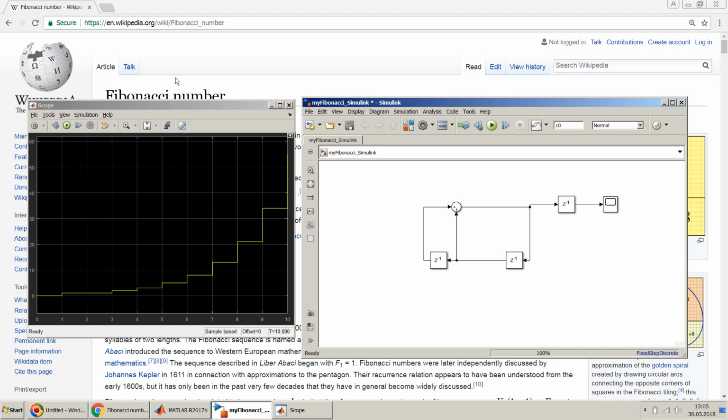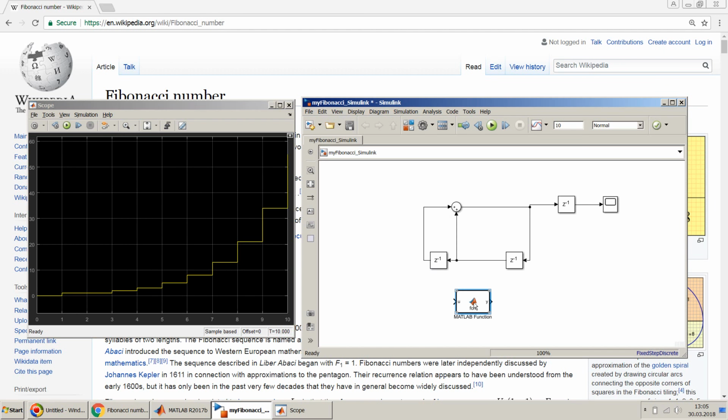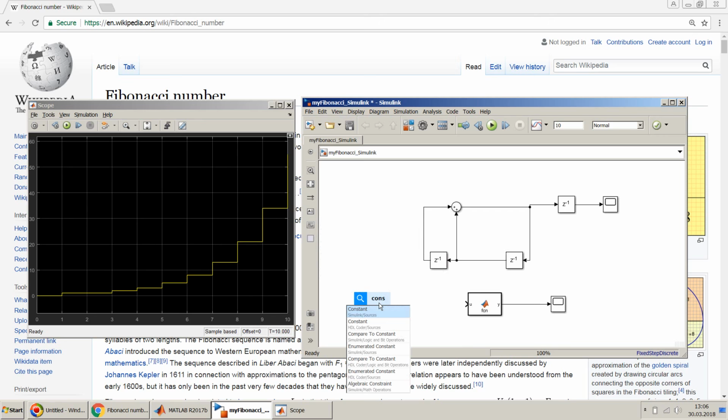What we can also do very quickly in this video is verify by running our MATLAB function in Simulink using the MATLAB function block, which is somewhere around here. We'll call our MATLAB function from this particular MATLAB function block and see the output in the scope. Let's see if this holds true. So number of arguments 1 is fine, and for input I will give a constant value, for the first time let me give 5, and this should be fine.